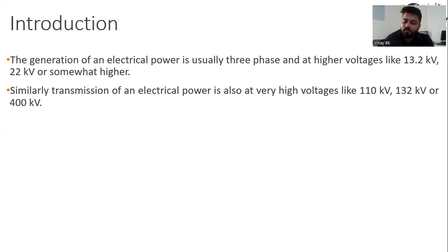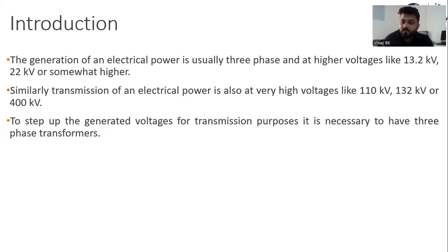And also, if you consider transmission of electrical power, it also usually has higher voltages like 110 kilovolts, 132 kilovolts, or 400 kilovolts. For that also, three-phase transformers are required to step up the generated voltages for transmission purposes. It is necessary to have three-phase transformers, because if you are generating 11 kilovolts, to step up that 11 kilovolts into 33 or 66 for transmission purposes, it is necessary.